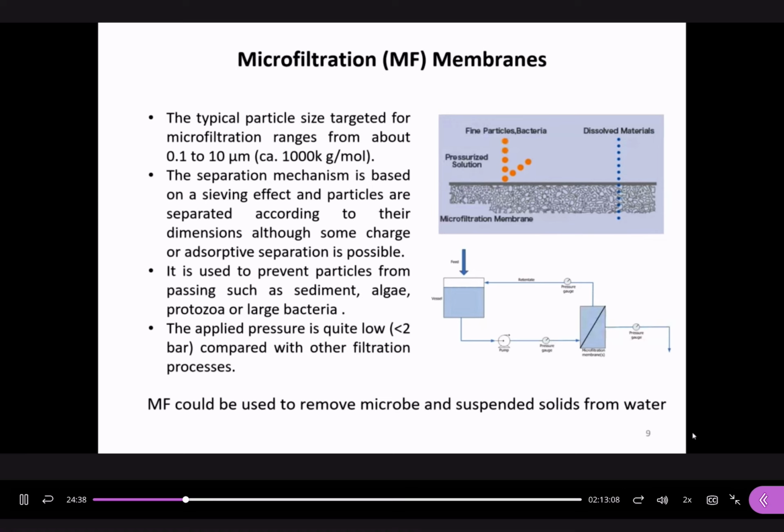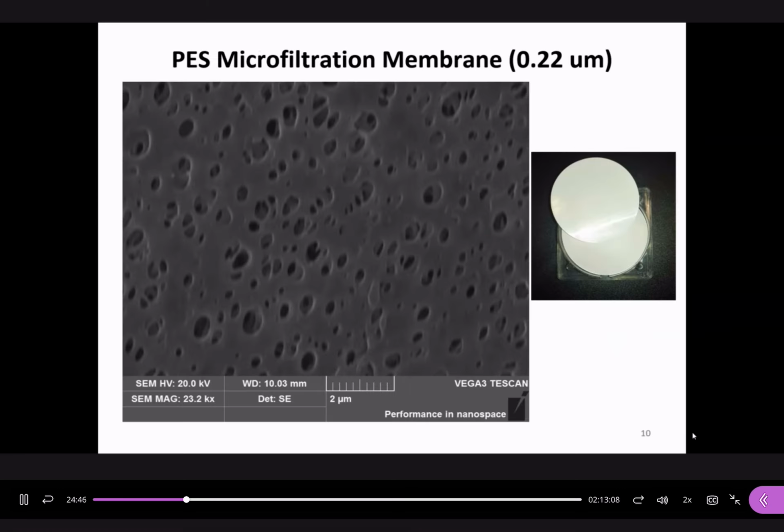And we do have some microfiltration membranes. Where are the samples? Membrane samples. Okay, you can take a look. Some coupons like this, right? And we take photos of these membrane coupons under a scanning electron microscope. We magnify them by 23,000 times. So we can see the pores. And the nominal pore size is 220 nanometer. But you can see the pores have varied size. It's not all 220 nanometer. Some are large, some are small. And it's made of polymer. This is the top view.